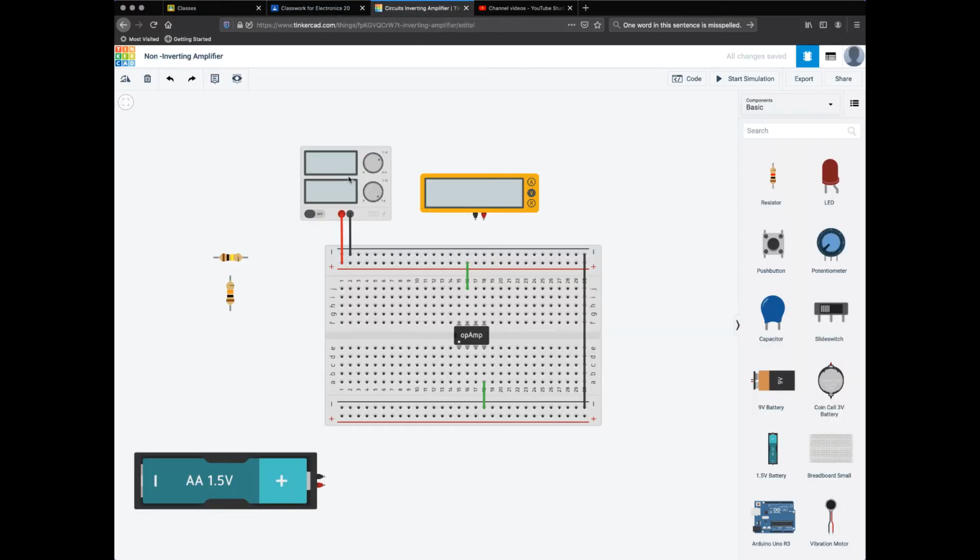So here's how I've done it. I have a power supply here, which you can see is running at 22 volts. And I've connected it into my breadboard so that I have ground there and my 22 volts there. Over here, you'll see that I connected the ground on this side of the board all the way over to the ground on this side of the board. That means I have ground everywhere that I want it. The common ground, if you will, to connect things to.